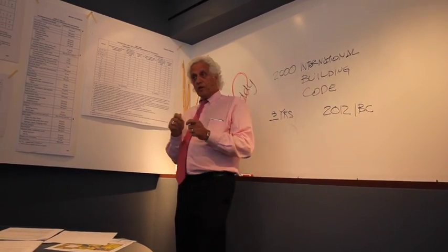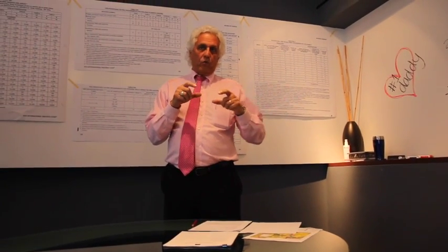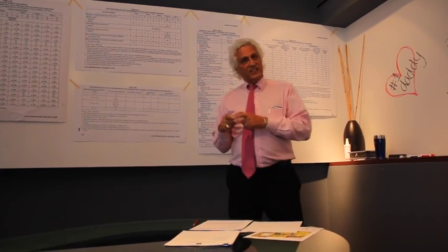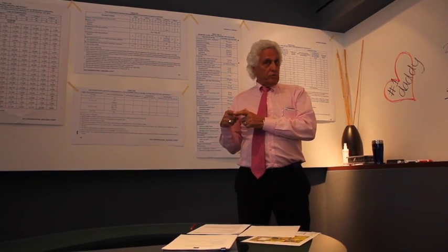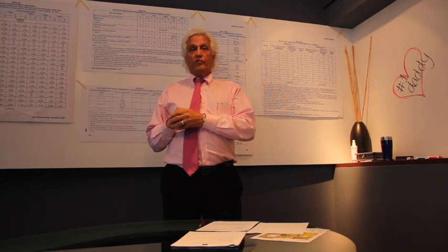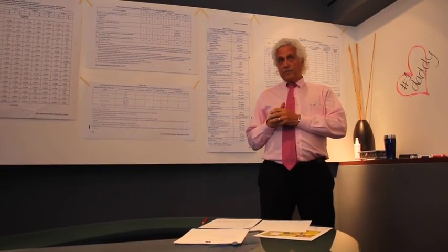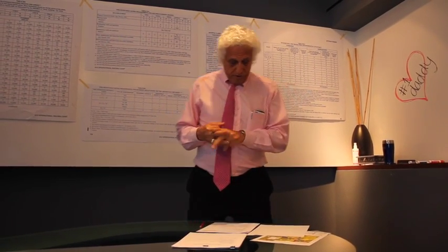So there are differences. The other big difference in the American Disabilities Act is that where the building code mainly addresses new buildings, the American Disabilities Act also addressed existing buildings. So if you had existing buildings, you had to then renovate your buildings to comply with the American Disabilities Act. And that meant providing parking spaces with certain widths and striping and signs, having curb cuts so people in wheelchairs could come up on ramps, changing the door widths of your public areas. So it had an implication, and there's been many, many lawsuits as a result of that.